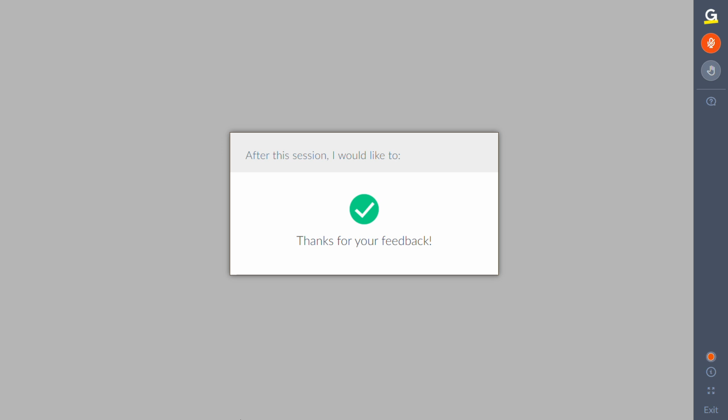But in case that is not possible, you can go with the CAD import module. When you have the CAD import module license, you can import any of these SolidWorks or CATIA or Pro-E or NX file formats within COMSOL. But in case you don't have the CAD import module as well, you can export the CAD geometry as a Parasolid from SolidWorks, or it can be IGS. You can export it in such standard geometry formats, and import it within COMSOL.